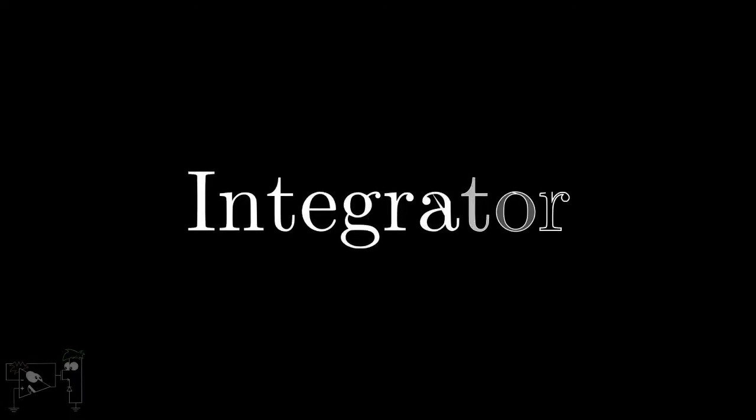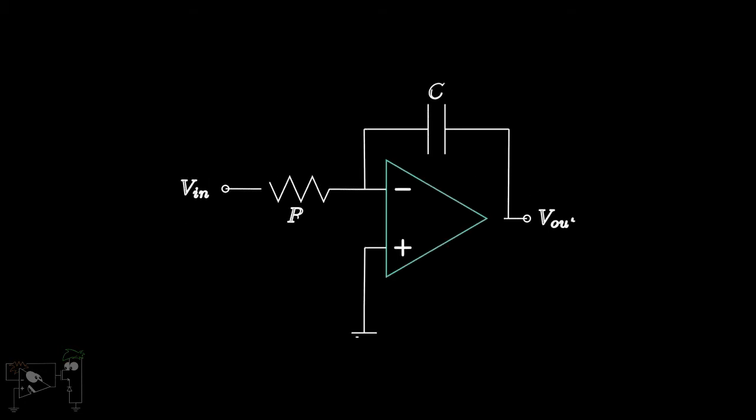In this video, we'll see how an op-amp can be used as an integrator. Let's look at our inverting amplifier. However, this time, we'll replace the feedback resistor with a capacitor. Here, by replacing the resistor by a capacitor, the only thing that changes is the feedback factor. The op-amp is still in negative feedback and hence, we can use the virtual ground concept.